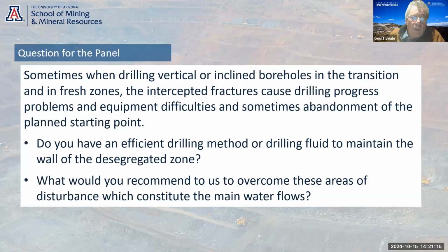If you're drilling wells and you have issues, then sometimes you have to go to casing advance or sonic. There's a number of ways to do it, and it depends what you're drilling. You may want to mud up the hole depending on what it's going to be used for. But the problem with mudding up the holes is there's a tendency to damage the fractures.